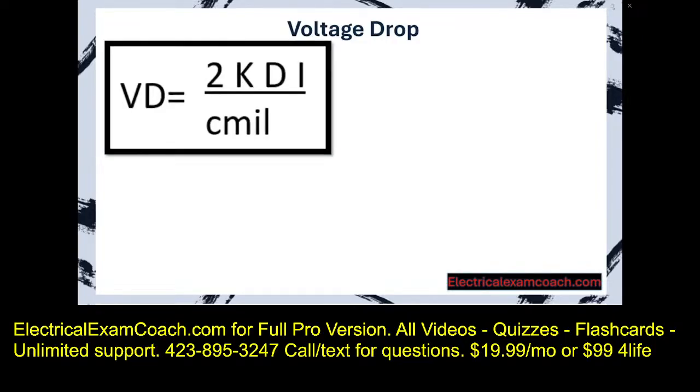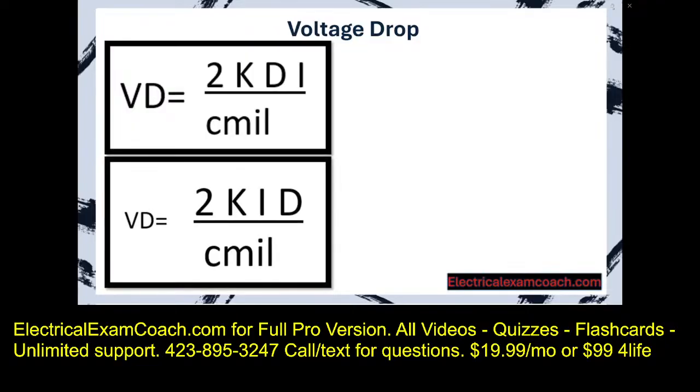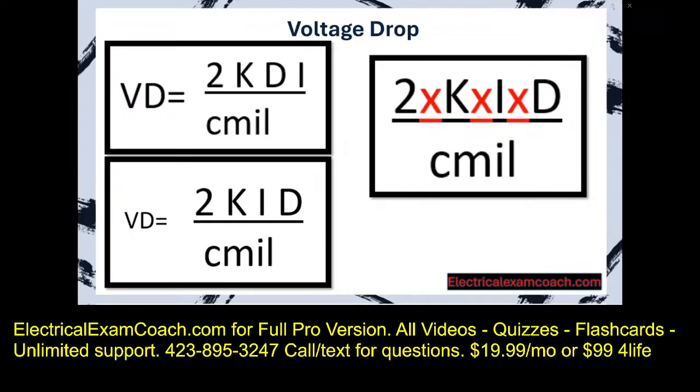Voltage drop equals 2KDI over C mil. And that is an excellent formula, and it's actually the one that I use. But I've rearranged it so it's easier to remember. I do it like this: 2KID over C mil. Easy to remember and easy to plug in. And what this is, just like previously in the program, is implied multiplication. So it's going to be 2 multiplied by K, multiplied by I, multiplied by D, divided by C mils.